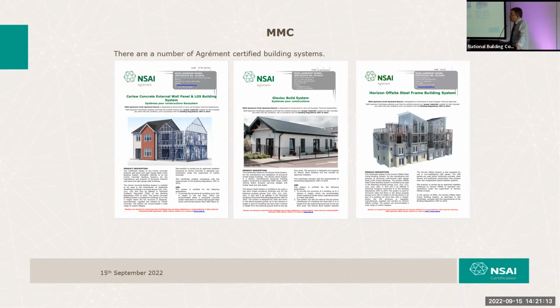And I do believe that as part of the initial submissions, more and more developers out there are being asked to provide a suite of typical details that they build to demonstrate that they have thought about thermal bridging. And as I said earlier, it's not that we're going to be modeling from here to eternity. It's 20 details. Get a pack of 20 robust details. How those pieces of Lego fit the final jigsaw puzzle is incidental, but that's probably a safe way to go, I think.